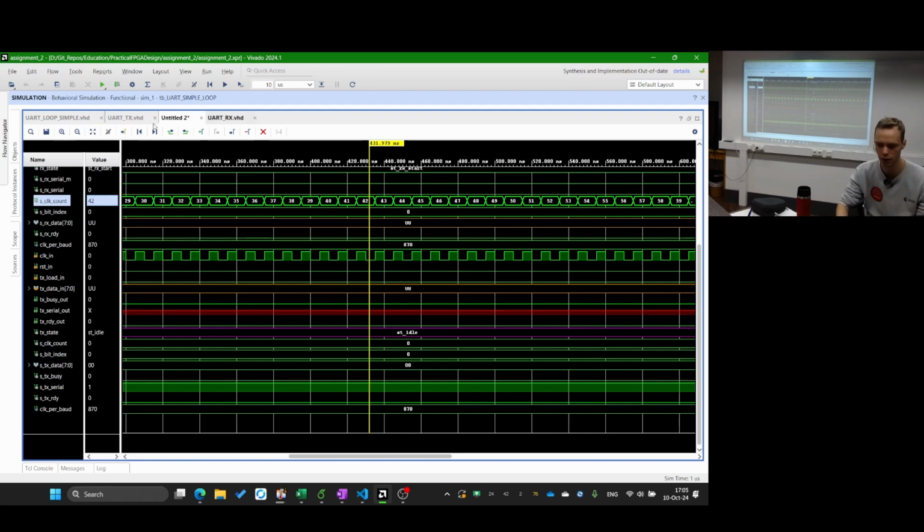Because right now, I have multiple clocks in here. I have a clock here, and I have a clock up there, and they're all the same because that's a clock which goes through the design, right? I maybe don't want to have that ten times because it's just going to clog up and make it less of an overview. But then I would need to drag all these different signals or do it manually. So I really recommend making a script at some point which loads all the signals in automatically, because then every time I run my simulation, that is called, and I get the simulation immediately in the view, in the window, in the time frame, with the signals, in the colors, as I need it.